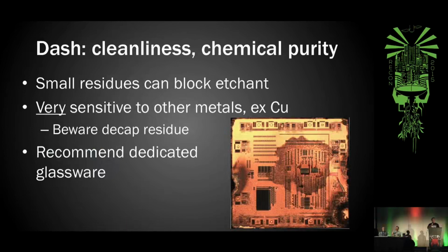So the next issue that you run into is that things need to be very high purity. I think this is one of the issues I ran into using the early hardware store chemicals: they had different additives in there that were causing interference. The picture to the right, for example, talking about interference, those little circles on the left and the right, I believe those are from tweezers that grabbed the die, and they deposited a very small amount of residue onto the die, and that was enough to completely ruin the reaction on the die and cause lots of problems.